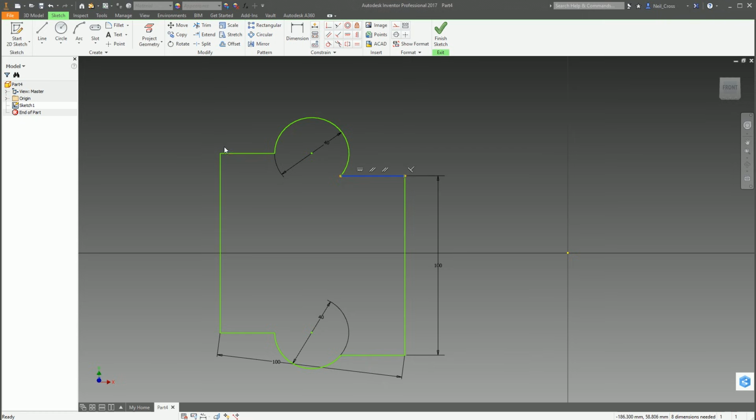So trimming objects can cause some things to break, and as you can see, it's done just that. We've broken this top edge and this bottom edge into two halves. So this edge is now no longer one straight horizontal line. It's now been broken up. So this is where you would additionally create 2D constraints manually. Not applying those 2D constraints manually would be devastating to the sketch. It just wouldn't work. So we need to now add in some 2D constraints to make sure that we capture the intent of this design.